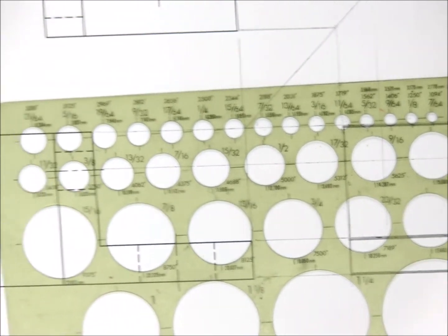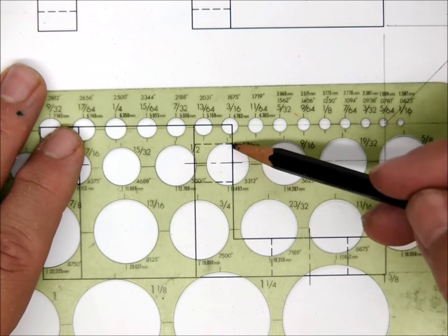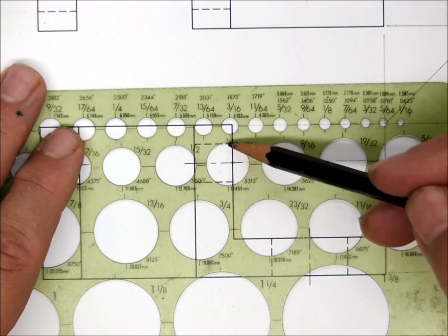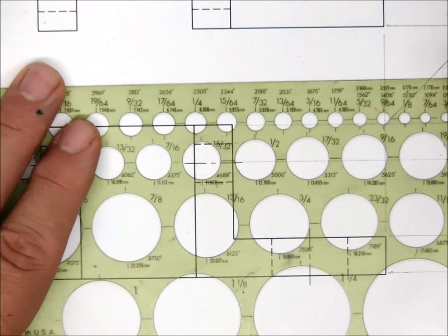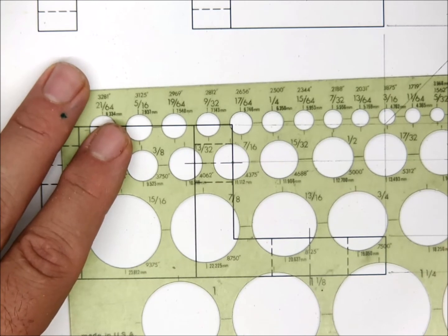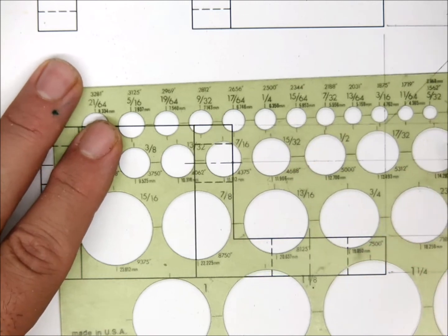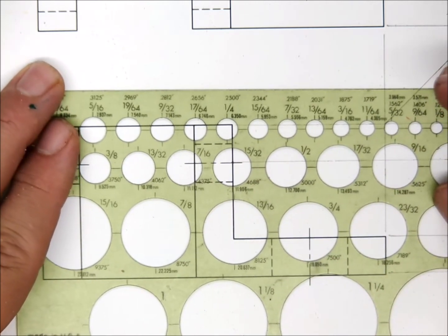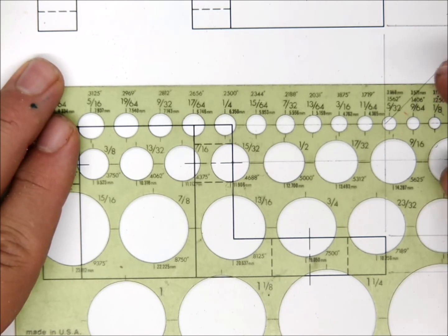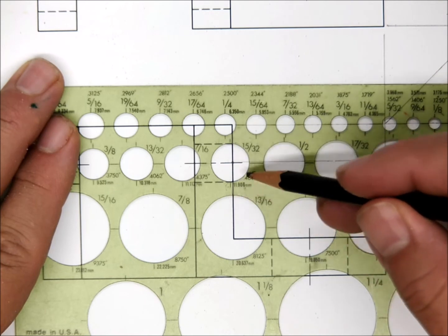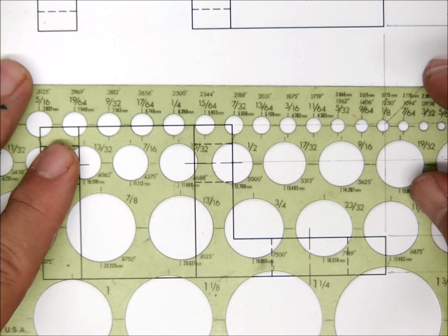What I want to do is go over to my drawing here, and see how big this hole is. So I can use the center line or the hidden lines that are there to get an idea of what size we're talking about. And let's see, 7/16, too small. 15/32, kind of a weird size. That looks really good, but you know your pencil is going to be inside of it, so that'll actually be too small also. The size we're looking for is actually a 1/2 inch diameter circle.